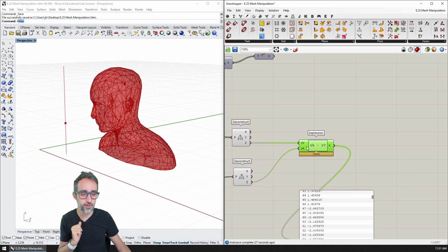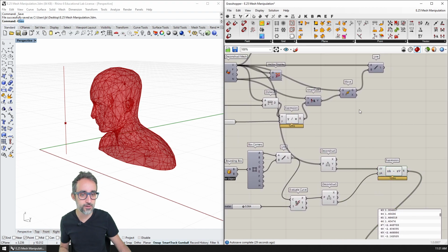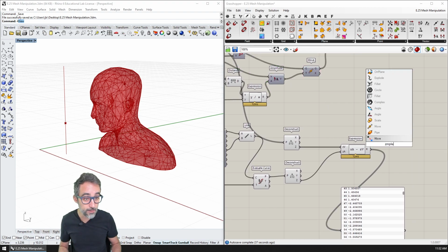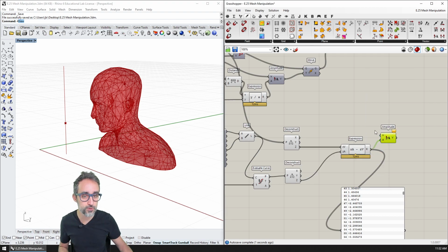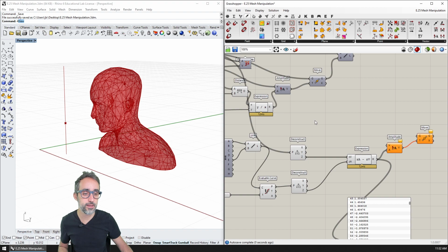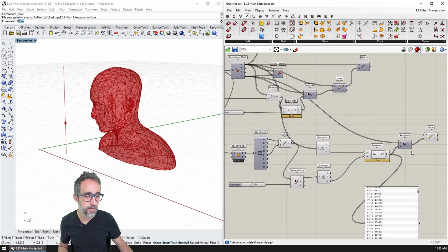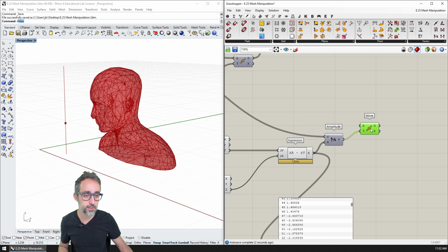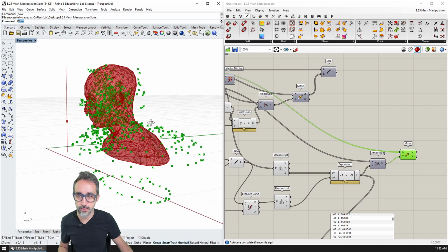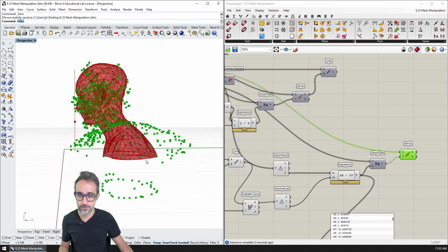And so if I now take all of this and use this expression to define the amplitude of the vectors that I'm going to use to move my, so I'm going to take the normals and set them to this amplitude, and then take all the vertices and move them by this much. So you can see that now the vertices on the bottom are moving a lot and the ones on the top are moving very little.